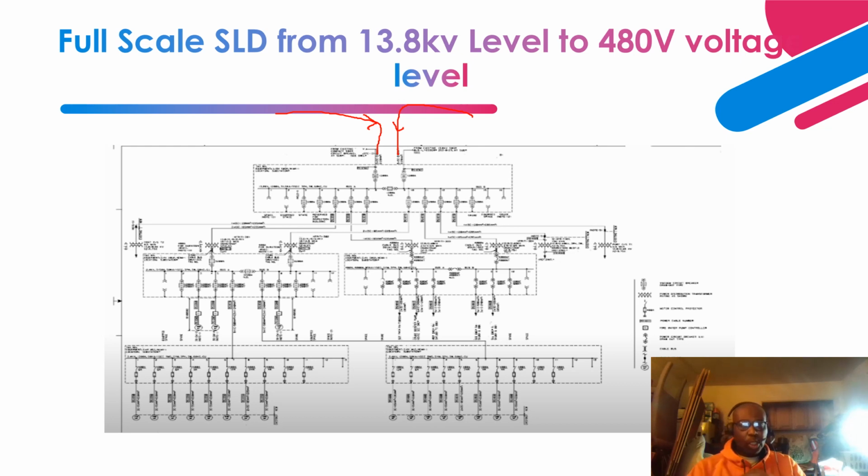Okay, so you can have different medium voltage 13.8 kV switchgears in the facility that are interconnected with each other. This can come from another medium voltage switchgear located in the same facility. So these medium voltage switchgears are interconnected and cascaded together. So you have a 13.8 kV feed from a medium voltage switchgear. This is the circuit breaker that comes in here, right?